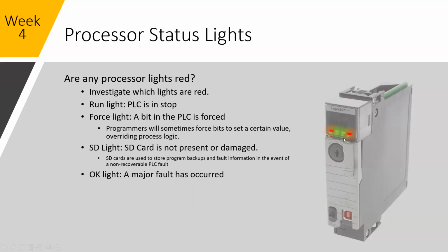The force light. Forces are used by programmers to set bits or values to specific values that override process logic. I try never to use them. In some cases, you have to if you're troubleshooting other code and you don't want to edit it. You can force outputs on or force outputs off.